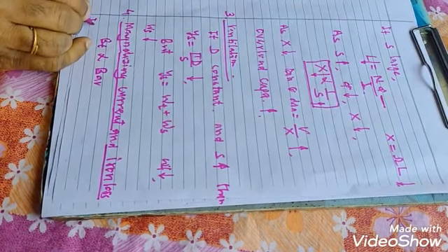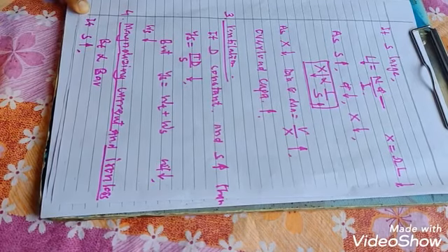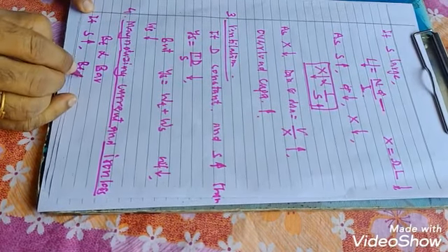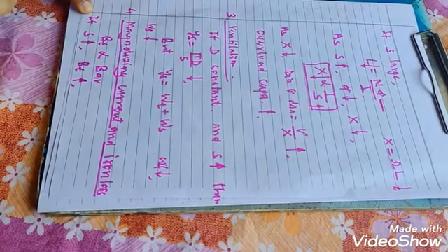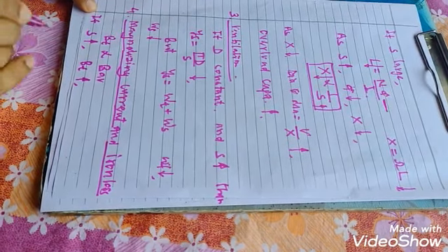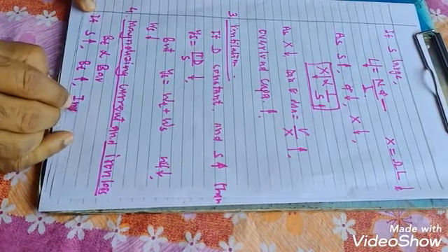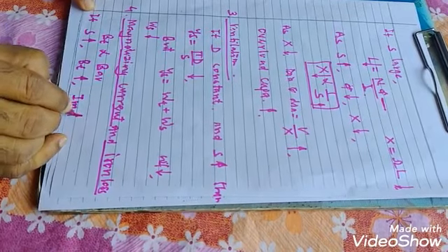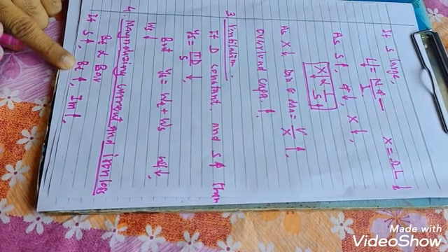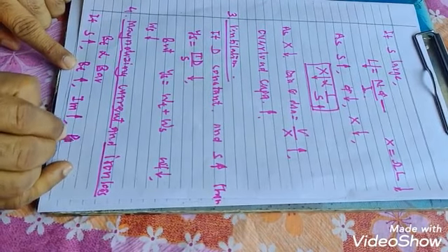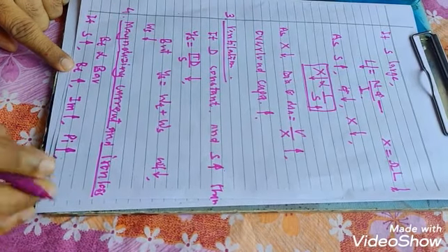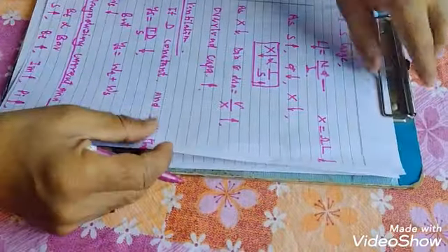So if a large number of slots is selected, the flux density in teeth increases, so that the magnetizing current IM is increasing, and as flux density Bt is large, the iron loss Pi in the teeth is increasing, and therefore there is overheating of the teeth.